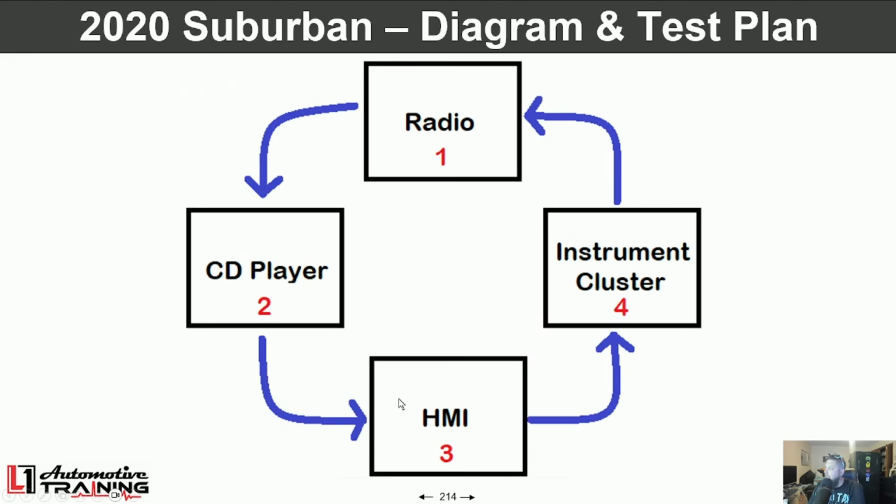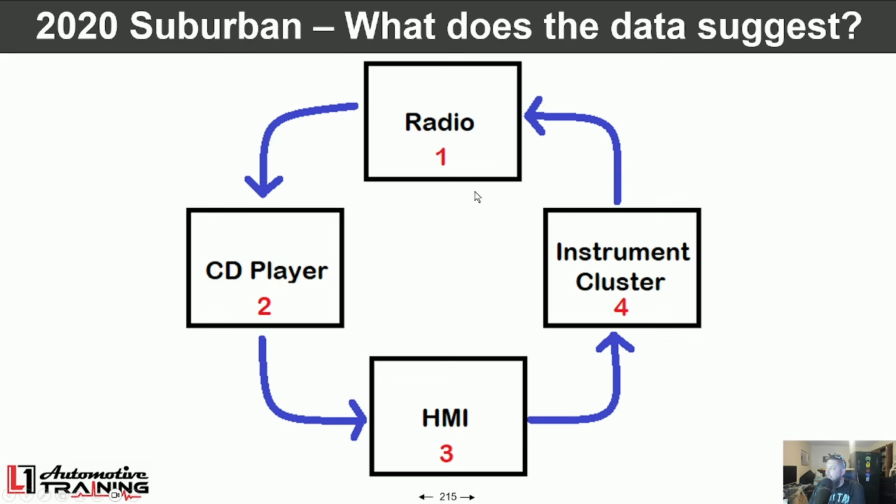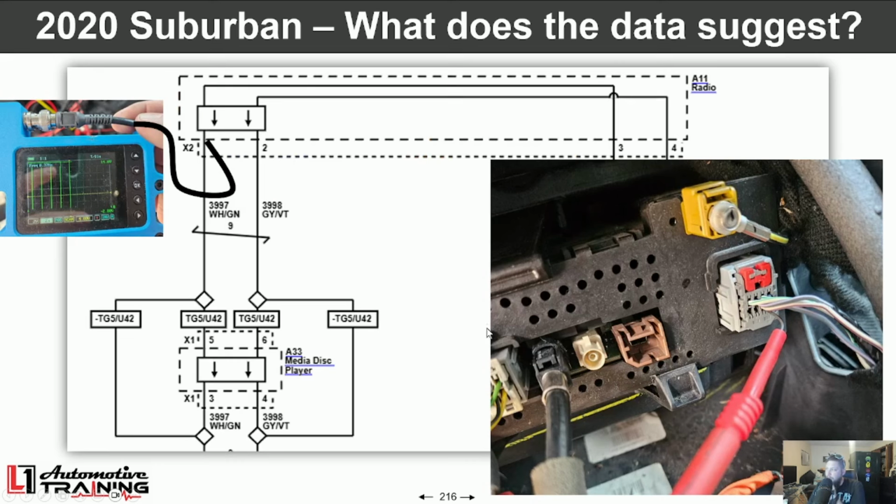And if that's the case, redrawing the diagram here just to get a better visual representation, our 3 modules not talking and the one that does means we most likely have a failure that is physical in nature in this particular connection. So we're going to look at this and go, okay, node 1 radio talks, the rest of these don't, because the rest of them say unrecognized state. That's how we're grabbing that data.